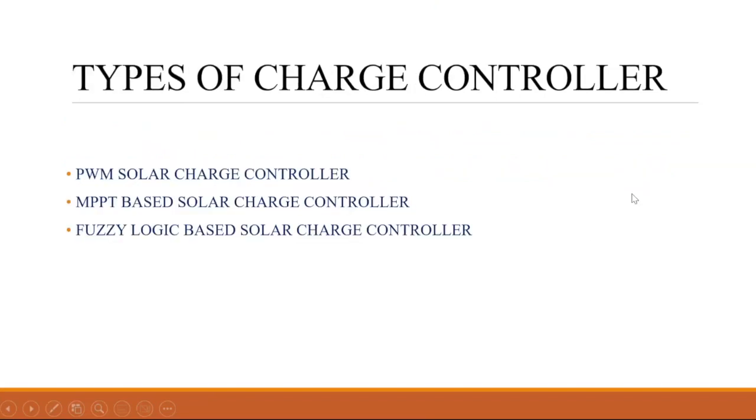Now there are different types of charge controller: a PWM based charge controller, a fuzzy logic based charge controller, and an MPPT based charge controller. Today we will be focusing on the MPPT charge controller, not PWM or fuzzy. Mostly we also prefer this MPPT controller, because it has good efficiency compared to PWM. And fuzzy is complicated to design. That's why today we will focus on the MPPT charge controller.